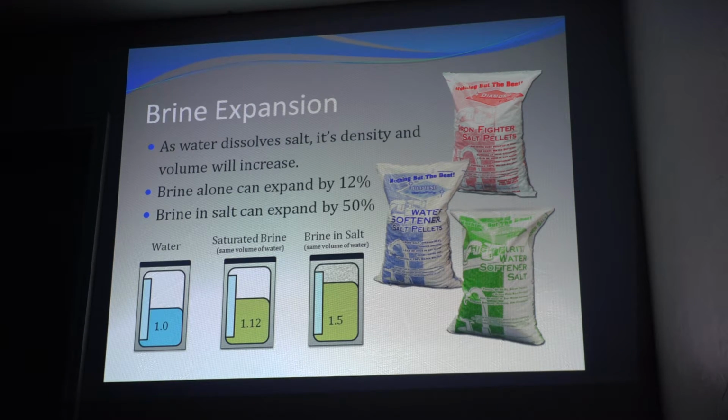And this exact thing happened the other day on the phone. The customer called me, said, John, our softener just started overflowing consistently. Oh, okay. Has anything changed? Did you change your salt product? Well, yeah, we just went from a pellet to a crystal. Like, that's why your brine tank's overflowing, your displacement is significantly more. Because it was consistently spurting out maybe a half gallon of water on the floor. It wasn't significant, it was just a little bit of water, just enough to push it up over that limit because their displacement was higher.